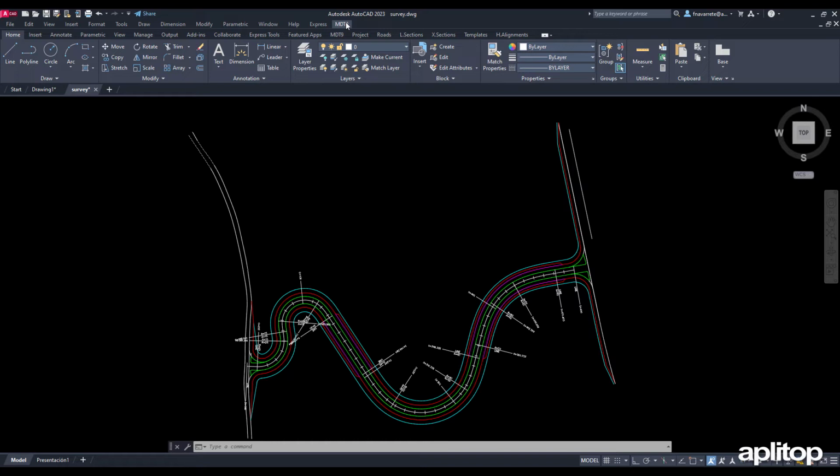To these polylines we are going to assign two different behaviors. The line of the curb foot, with the same height with respect to the polyline that precedes it, and the one corresponding to the height of the curb, which has a slope of 20 centimeters with respect to the bottom of the curb.